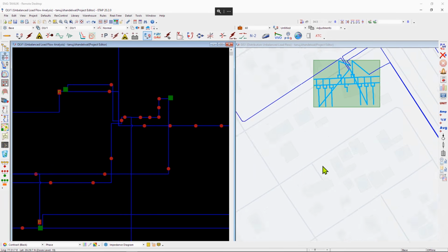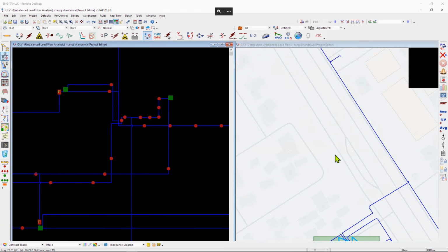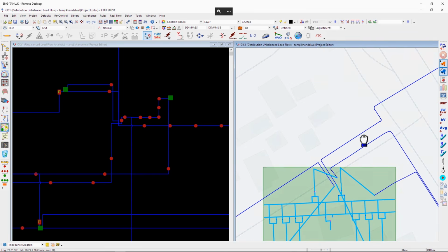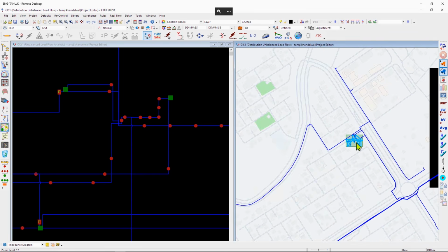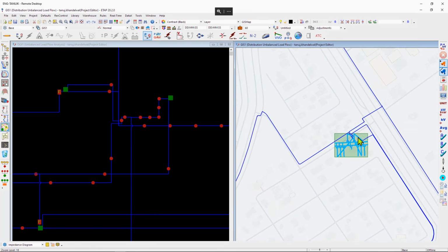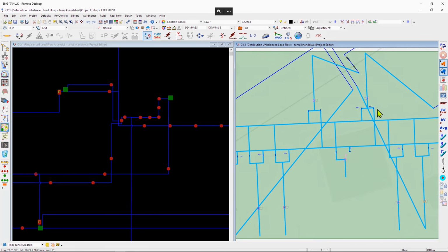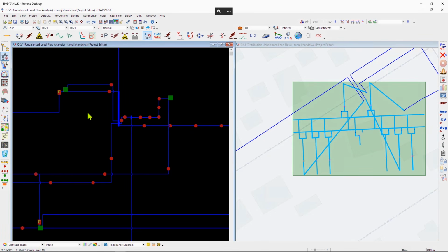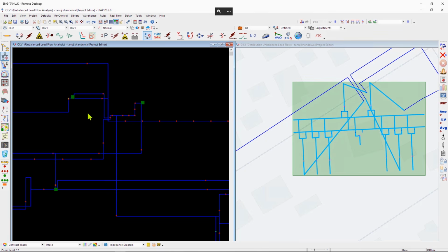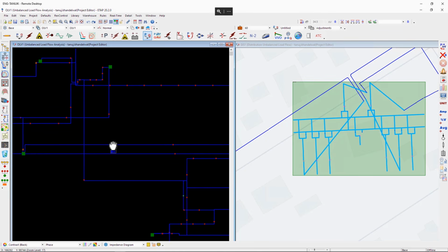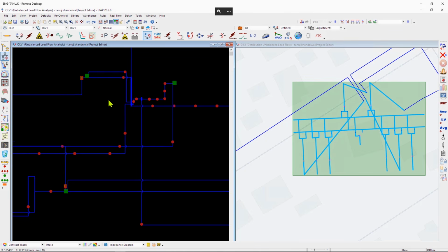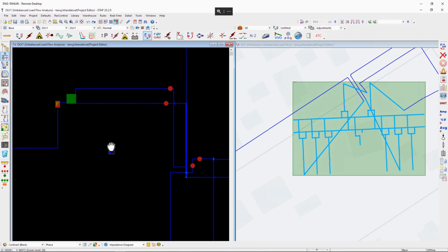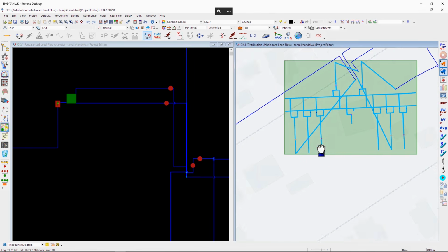This project has a GIS system and includes ETAP NetView. ETAP Intelligent Geospatial Diagram provides an editable environment for electrical assets and connectivity combined with geospatial data. Geospatial information can be imported from many third-party systems or can be modeled directly within the electrical geospatial diagram. NetView is automatically created from GIS and represents a model that displays the network highlighting the substation connections. The substations are easily identified along with the switches and breakers while removing all the details included in the feeder.